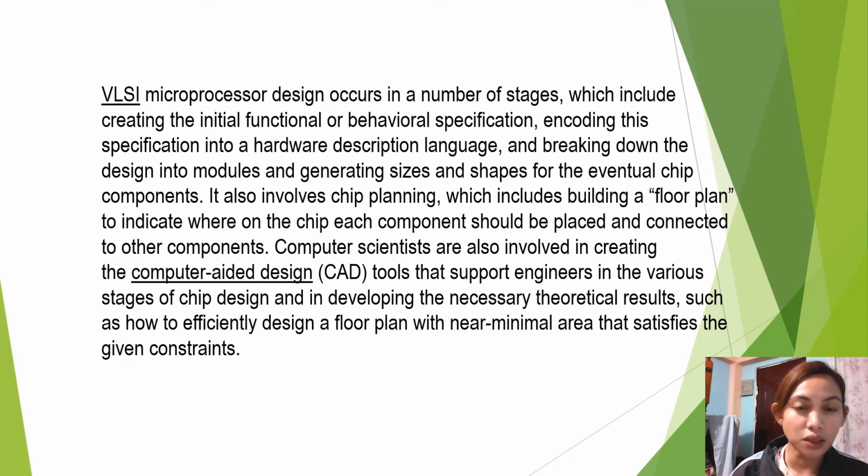VLSI microprocessor design occurs in a number of stages, which include creating the initial functional or behavioral specification, encoding this specification into a hardware description language, and breaking down the design into modules and generating sizes and shapes for the eventual chip components. It also involves chip planning, which includes building a floor plan to indicate where on the chip each component should be placed and connected to other components.